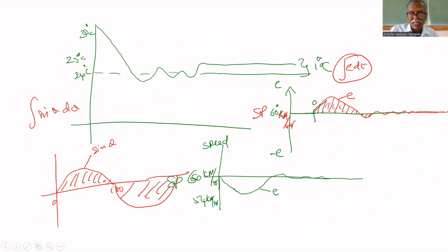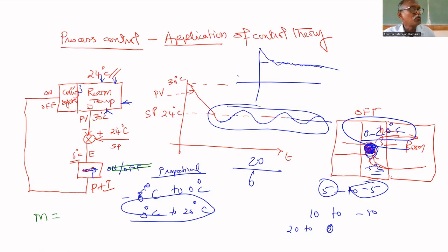Now that's all about PI. The D mode is there, which we rarely use. In our experiment, you won't use it. Anyhow, I'll tell you one more mode, that's why it is called a PID controller. The D mode is to speed up the response. D mode means derivative. This is the integral mode, I. Integral of E dt gives you the area under the error graph.